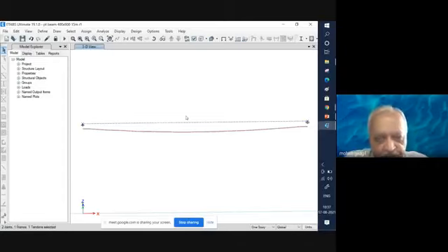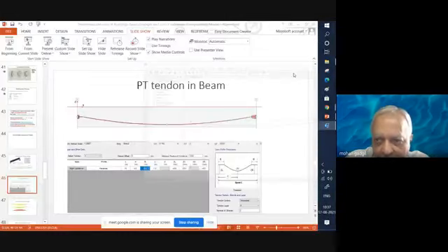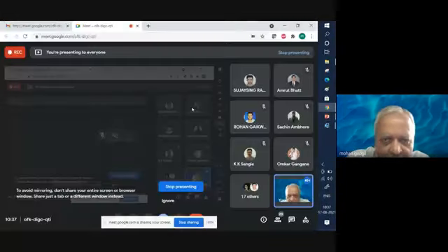Okay, now the complete load is applied on the given structure, and now we say that the run command is given for ETABS. The entire process is complete, and now we can see the results of the analysis in our presentation. So this is the way we prepare the data: the material data, the section data, the cable data, then the load data, and lastly the support data. With all this done, the results are now obtained.